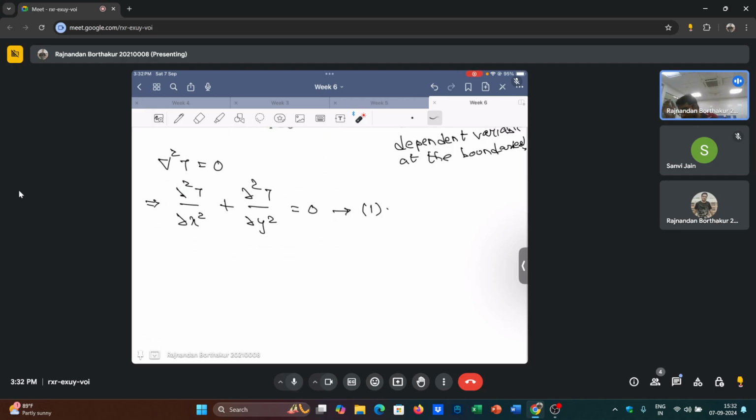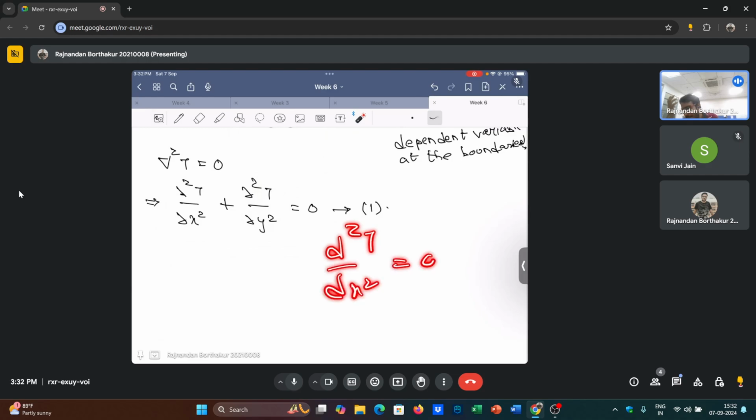Because it's very simple. So forget about these terms, then this equation is just an ODE. And then we solve multiple equations involving, let's say, d2T by dx2 equal to 0. If you remember, this was the 1D heat equation without heat generation. And we said that the temperature profile was linear and so on and so forth. In those examples, we have two boundary conditions, typically because this T was now just a function of x and it was second order in x. And that was an ODE.